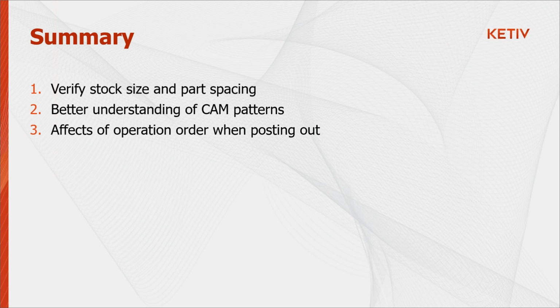Hopefully, you now have a better understanding of the CAM patterns and some of the options. Like I mentioned, CAM patterns themselves aren't really too difficult to understand. It's just the options in there that tend to throw people off. And then we have the effects of the operation order. The order by tool rearranges your toolpaths a little bit, so you want to be careful when posting out to your machine.